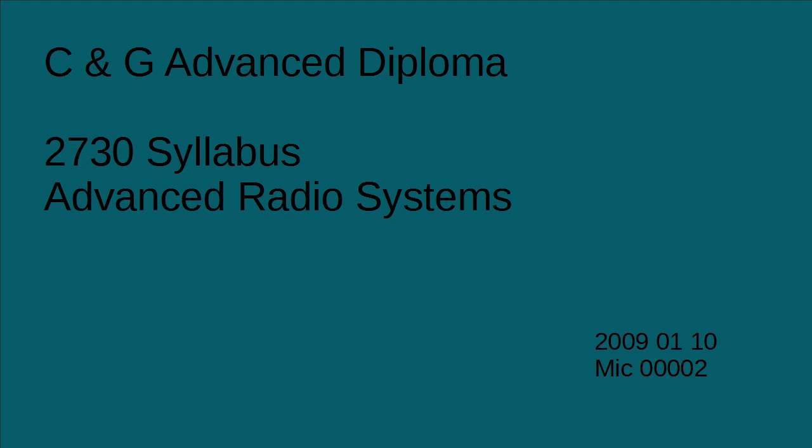Physical length is lambda by 2. Always remember, in a dipole, the electrical effective length, this is coming from electromagnetics, is not lambda by 2, it is lambda by 5. Please remember this. Electrical effective length is lambda by 5, not lambda by 2. Lambda by 5 is smaller than lambda by 2, you know that. So electrically all that length is not effective. Less length is effective. Right?